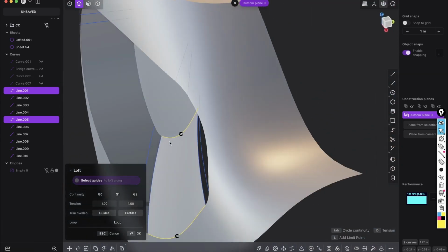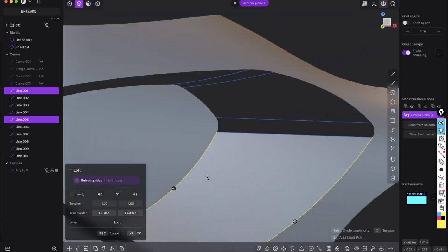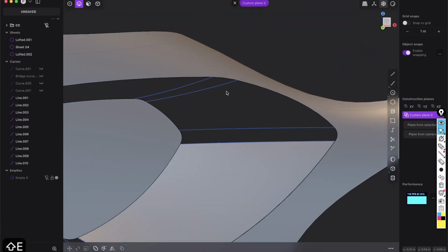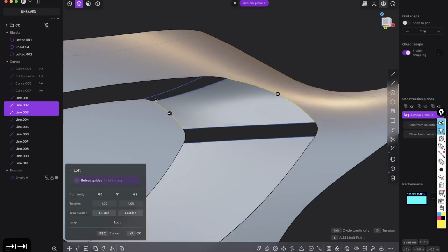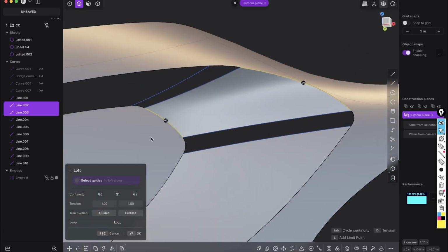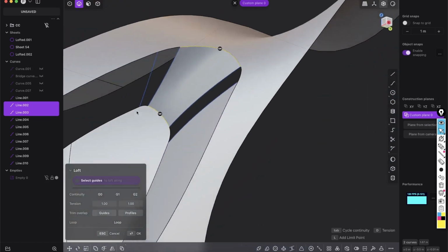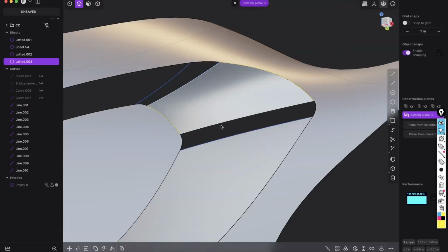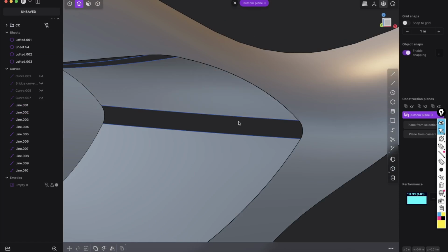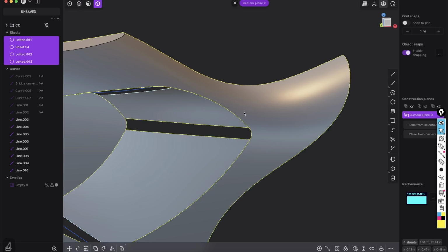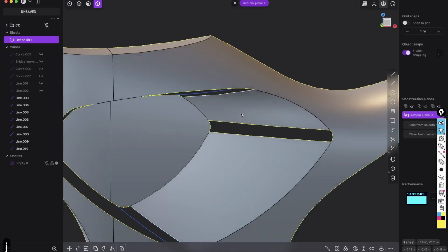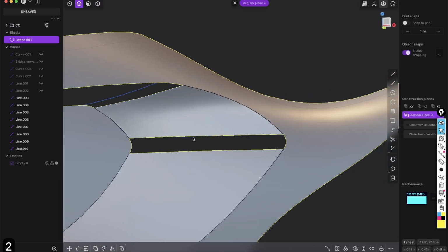And you see we get a beautiful surface here with some rounding. So let's do the same here again. Select first the long ones and loft, shift, tap so it's G0. And you see we are already getting here a little bit of some squeezing, but let's just try to work with that. And now we can delete those curves and press 4 and select all of those surfaces and join, because now we can just work better with that.